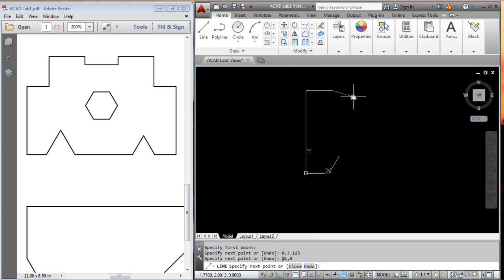Okay. Now, the next thing I want to do is go up to this corner, as we see in the drawing over on the left. So, to get there, it says that I'm setting it 1 inch over, so if I remember that, I'm good. And I need to go a total height of 4.5. On the drawing, it says 2 times 4.5. That means from this bottom to here is 4.5, and from this bottom to here is 4.5. So that's what the 2 times means. The 2x means it happens at 2 different places. Much like the 3.125 over here says 2 times. It happens once here and once here.